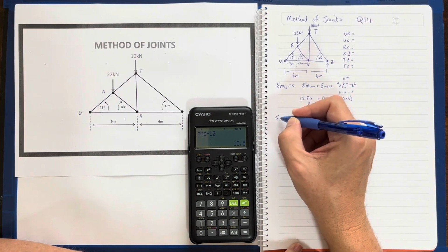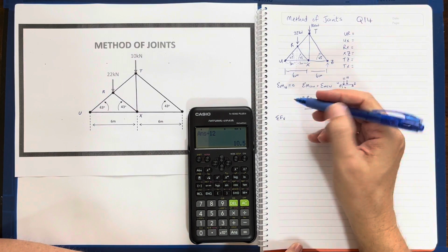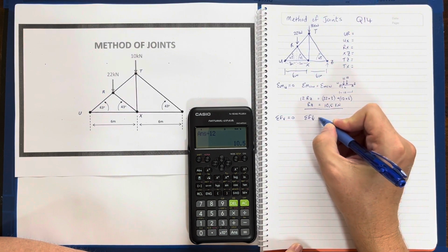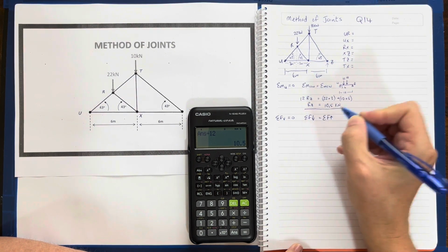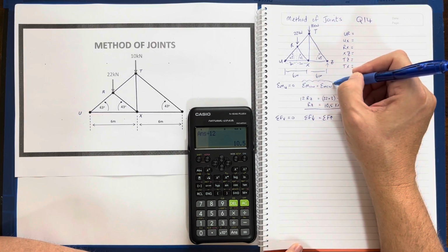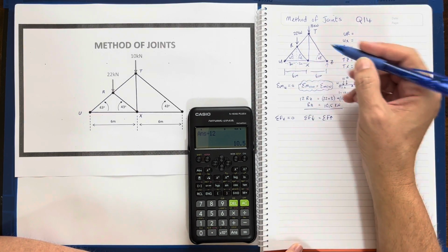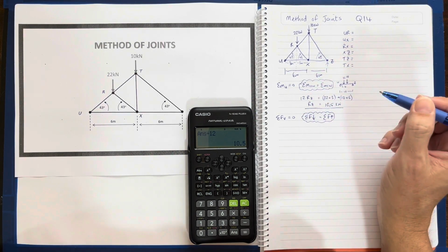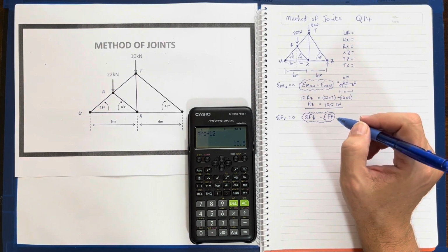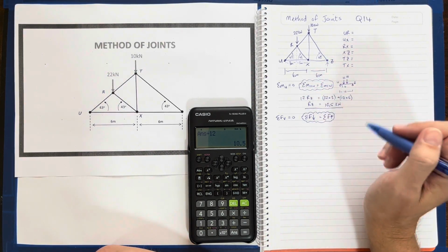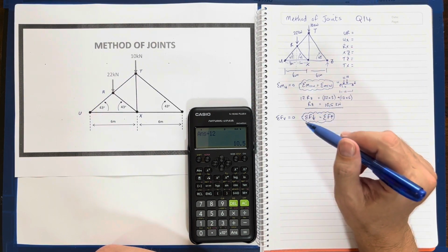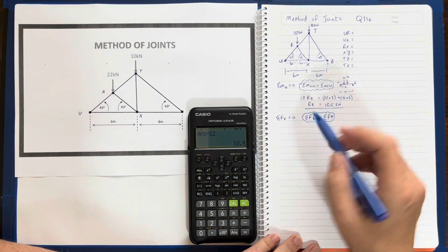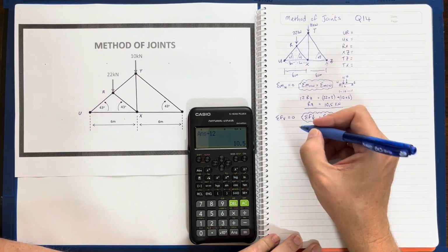And then very quickly, sum of forces vertical, because now I can just add up the other forces. That is going to be sum of my forces down equals sum of my forces up. I'm not going to write those all of the time. I've written them here already, knowing that this entire truss is in equilibrium. My forces down will always equal my forces up. My counterclockwise moments will always equal the sum of my clockwise moments, and it'll be the same for horizontal. So straight away I have forces down, 22 plus 10.